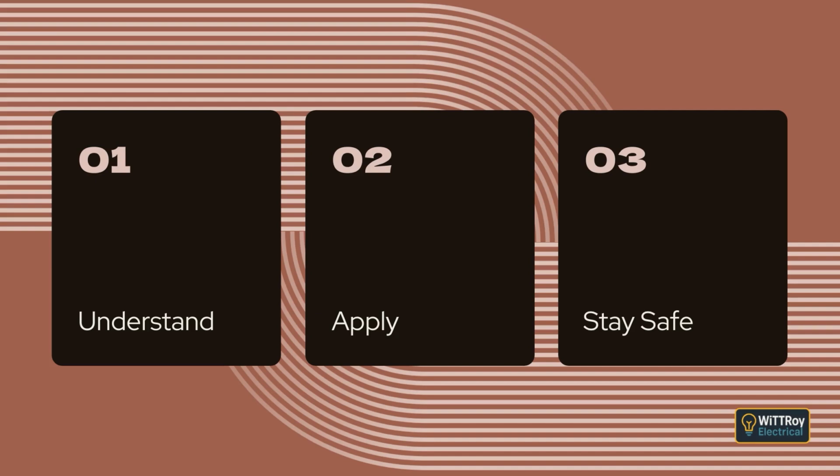Clause 3.9.8.3 Segregation of different voltage levels. Cables of high voltage circuits and low voltage or extra low voltage circuits must not be installed in the same wiring system unless effective segregation is provided. Low voltage and extra low voltage circuits may share the same wiring system only if the cables provide equivalent protection or the cables are enclosed in separate compartments with continuous barriers.